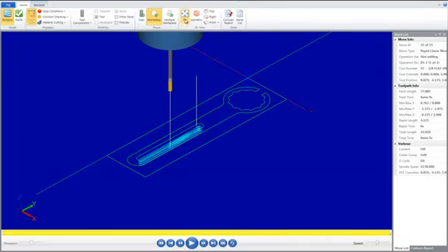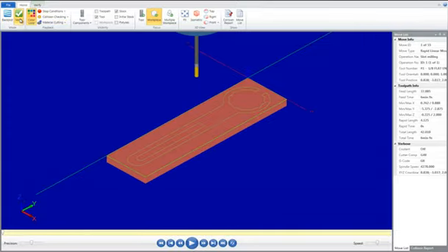Now we will simulate the toolpath and Verify. From the Mastercam Backplot Home, select the Verify button. Ensure that the following are enabled: Tool, Stock, and Workpiece. Verify mode shows the path the tools take to cut the part with material removal. This display lets you spot errors in the program before you machine the part.